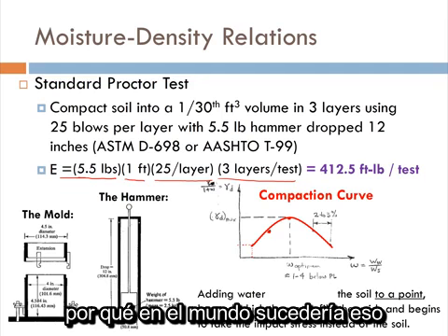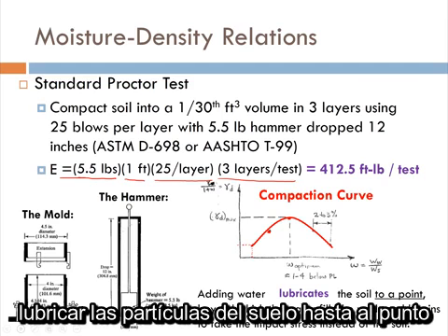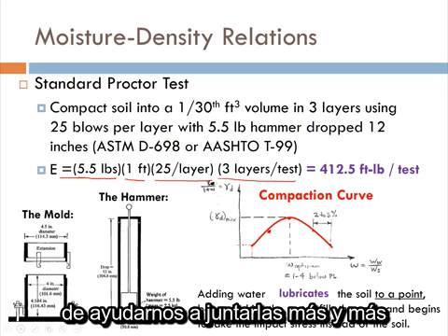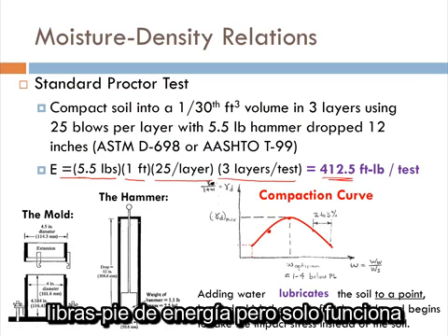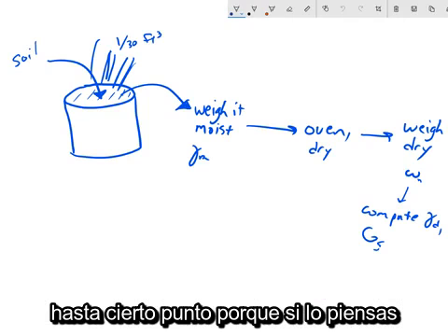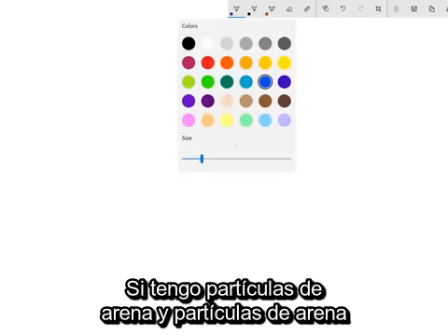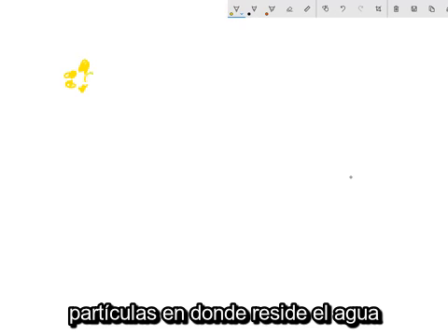Now, why in the world would that happen? Well, because adding water is going to lubricate the soil particles to a point and help them get closer and closer together when we add this 413 foot-pounds of energy. But it only works to a point, because if you think about it, if I have sand particles, sand particles, sand particles,